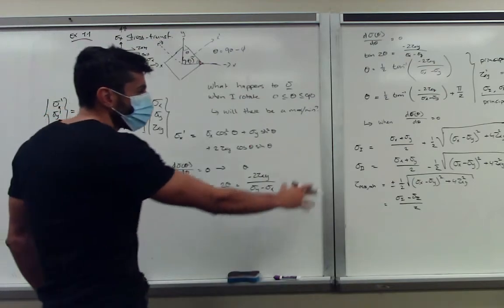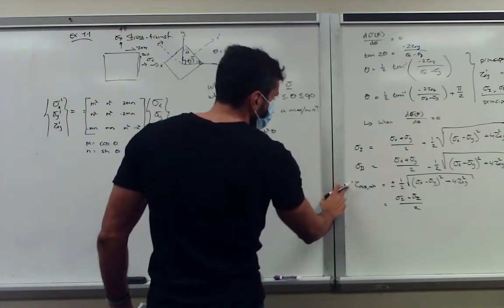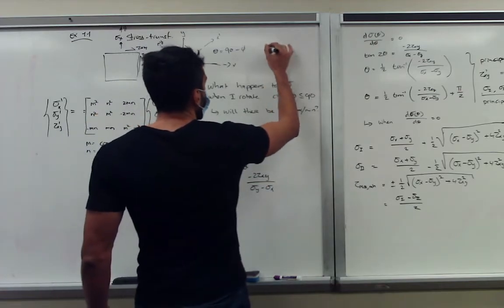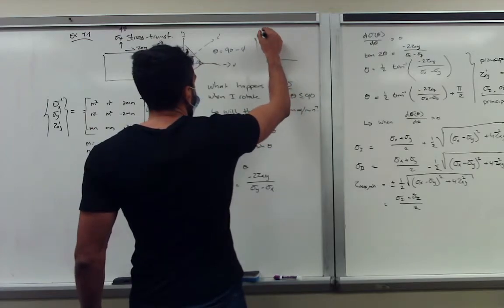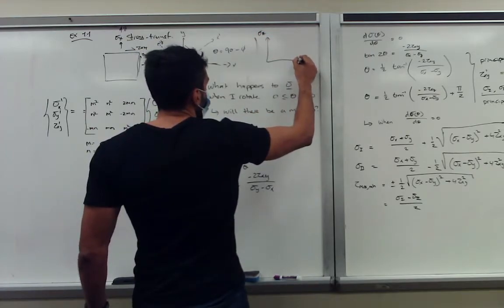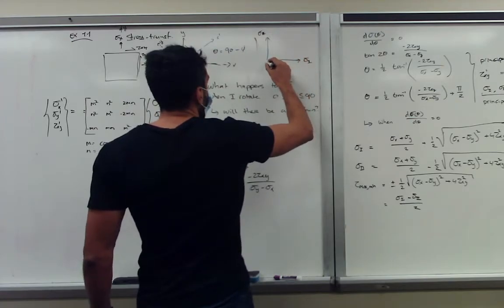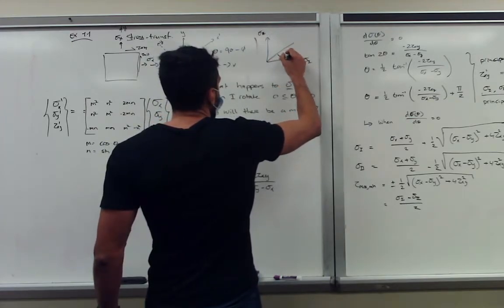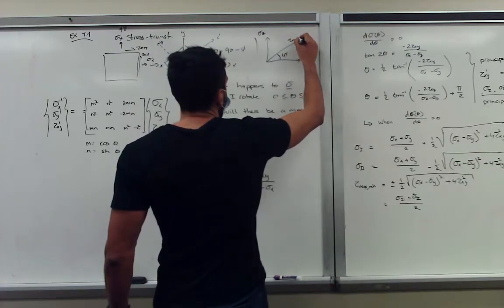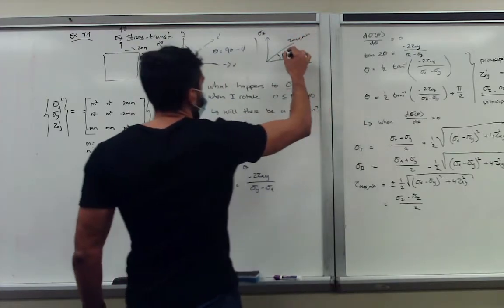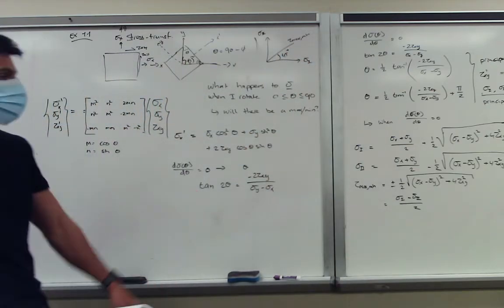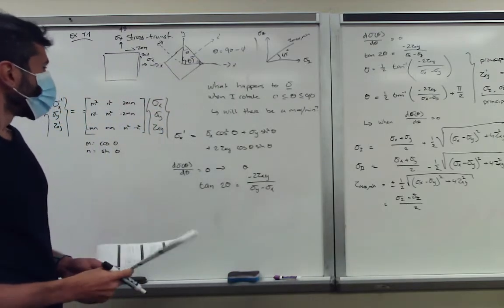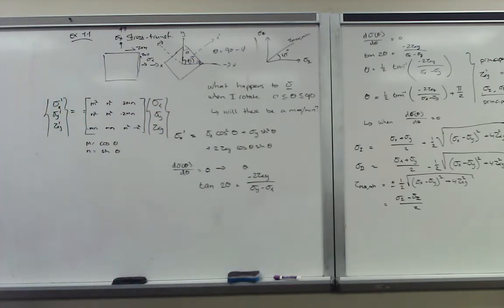Once we know these two angles, we can also derive that at 45 degrees to those angles, with our new axes defined by sigma 1 and sigma 2, there are maximum curves at 45 degrees. That's our tau max or min. That's also something you can get out of this. So we completed stress transformation matrices, and we can move forward.